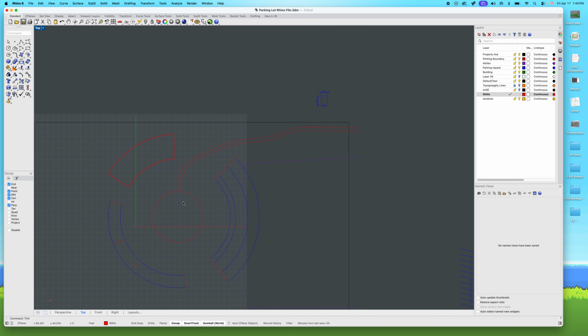Especially for some of us, if you've never used this before, you're like, oh my gosh, Pandora's box going on right now. But what else can I show you guys? Obviously, we can start doing the floor plan, and I do want to show a couple of things. So a little bit more detailed, like let's say this was just a regular stud and board, 12-inch wall, but maybe I want to line it with stone. Oh, sweet. But I don't want to line all the pieces with stone, so I'm going to go ahead and explode it. And I just maybe want this back wall to be stone.